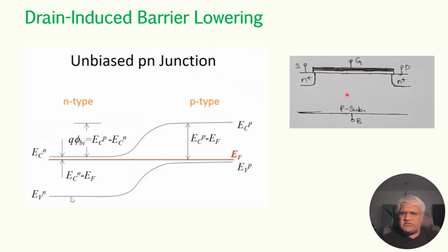Why we are discussing the PN junction is that this is the simple MOS transistor, with source, gate, drain, and body for the NMOS transistor. Here, if you observe, there is an N plus region and a P region, and the whole thing is P. Both P and N diodes exist. As such, both are the same. These are all back-to-back connected diodes.